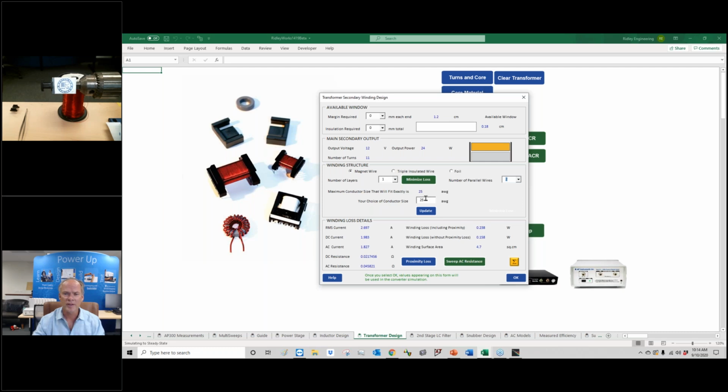And that comes in with a 25 gauge. Notice the losses here, that's 0.24 watts. If I did the big wire, it's 0.21. So we're talking 20 milliwatts difference. So let's choose one that's easier to wind for us, and it's easier to wind for the manufacturer. So the primary was 1 strand of 26, secondary is 2 strands of 25. Well, I might even go simpler and say, hey, let's use 2 strands of 26. So we stay with the same size wire all the way. And we give ourselves a little more margin for building up in the bobbin.